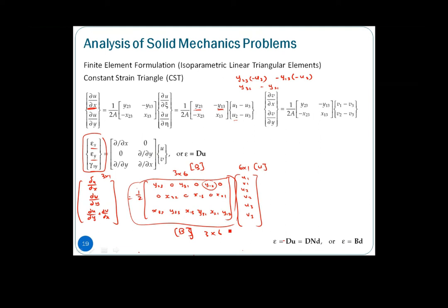If that is using isoparametric methods, they are basically sharing the same shape function under natural coordinates. So we make use of these isoparametric formulations to formulate our strains in terms of displacement: del u del x, del v del y, and del u del y plus del v del x.